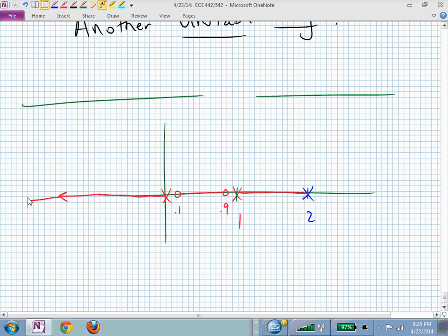How many infinite zeros do I have? So the only thing going off to infinity is going off at minus 180. These two are going to approach each other and then break away and come over here, aren't they? And one's going to go to that finite zero and another's going to go to that finite zero.